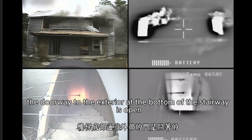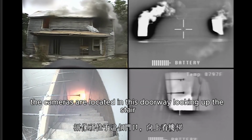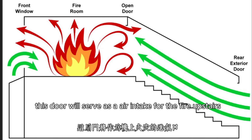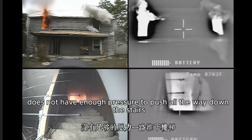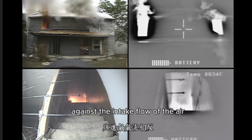The doorway to the exterior at the bottom of the stairway is open. The cameras are located in this doorway looking up the stair. This door will serve as an air intake for the fire upstairs. The upstairs windows are the only point of exhaust initially in the fire, as the smoke building in the hallway does not have enough pressure to push all the way down the stairs against the intake flow of the air.